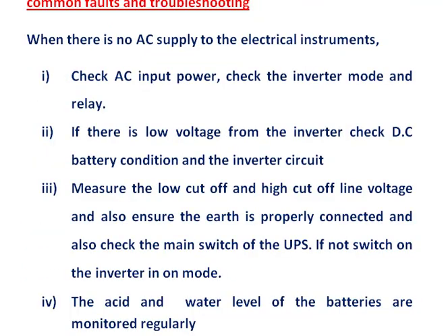What are the common faults found in this inverter circuit, and how are they troubleshot when there is no AC supply to the electrical instruments? First, we have to check the AC input power, whether the AC input power is supplied to the inverter or not, and then check the inverter mode and relay. Relay plays a vital role here to control the AC power.